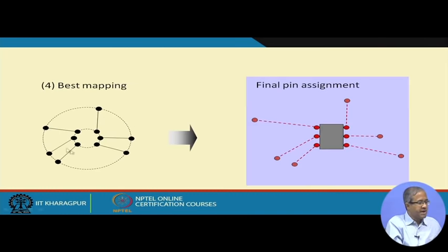Once you get the good rotation, this is the best rotation. So, you connect them in straight lines. Now, with respect to your chip, you replace them by your external pins again. Your 6 pins were there. Now, on the concentric circles your positions have been fixed. Now, you connect the corresponding pins to the corresponding points. This will be your best mapping. If by rotating the circle your original pin which was here has come here, you make it here, no problem, that will be a better solution.